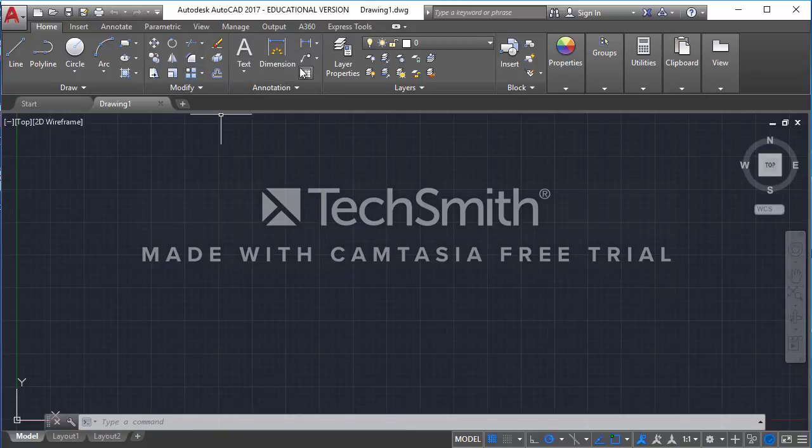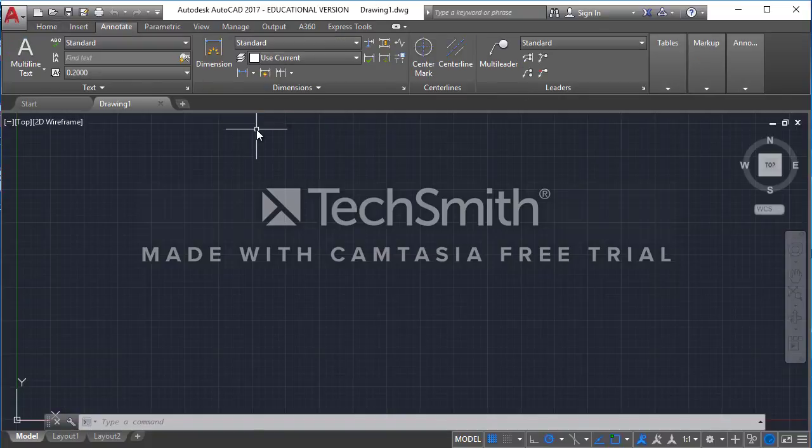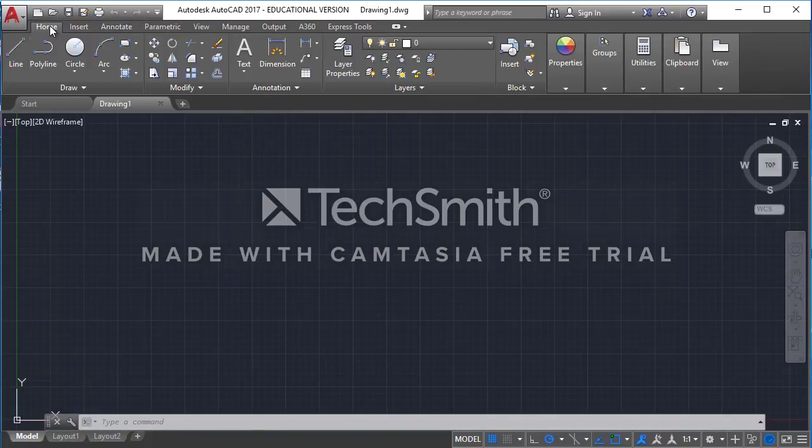Moving down the line, you also have text and dimension. A lot of what you see here under Annotation, you will also find if you click on Annotate. But the reason they put it under the Home tab is because they're giving you the most frequently used tools right here in one ribbon, so you're not having to go back and forth between the ribbons constantly.